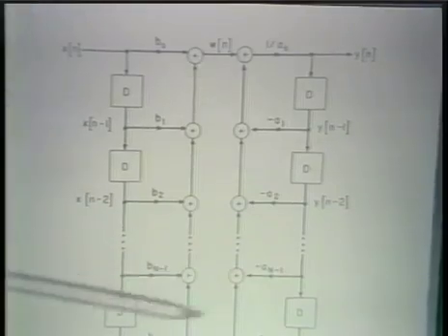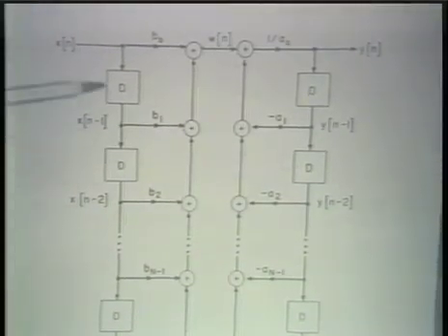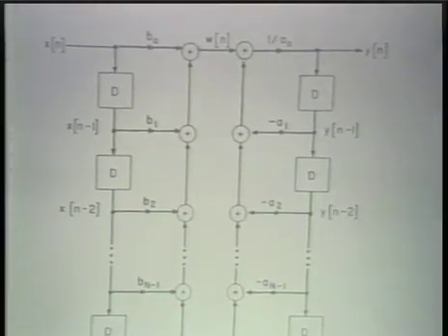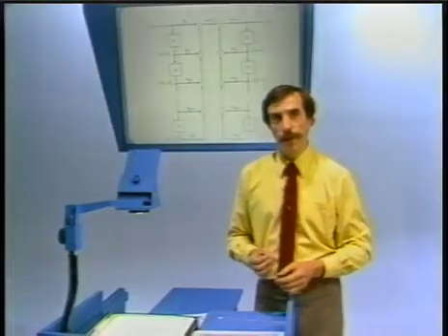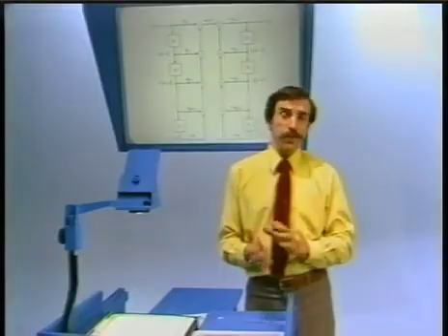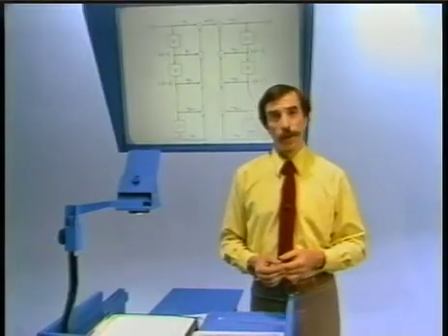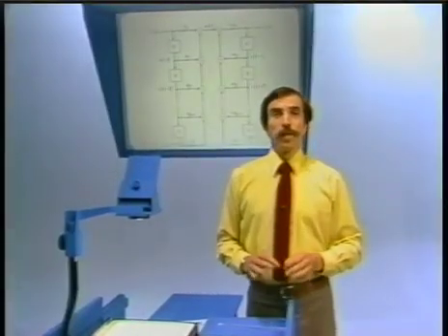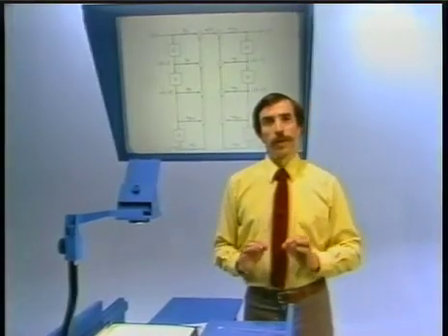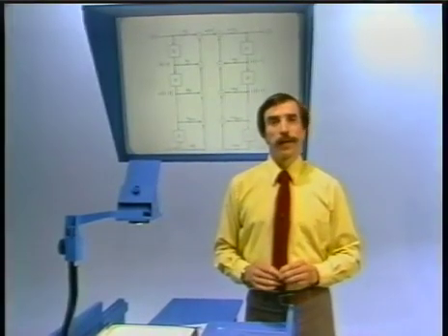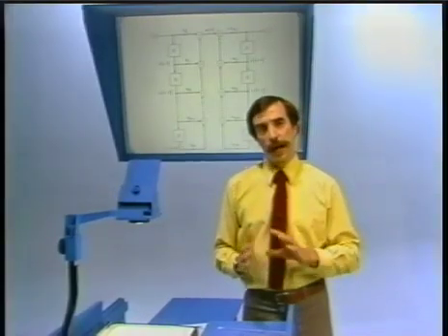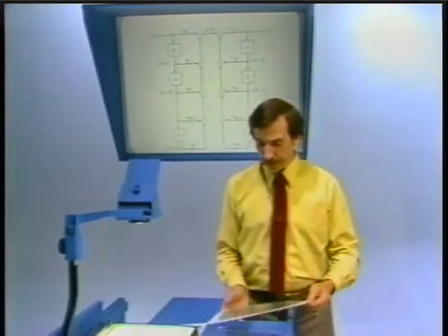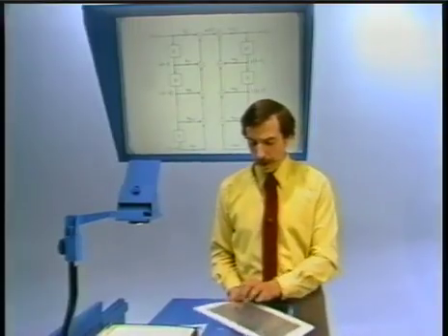And so this, in fact, then represents a block diagram, which is a general block diagram for implementing or representing a linear constant coefficient difference equation. Now, if you think about what it means in terms of, let's say, a computer algorithm or a piece of hardware, in fact, this block diagram is a recipe or algorithm for doing the implementation. But it's important to recognize, even at this point, that it's only one of many possible algorithms or implementations for this difference equation.